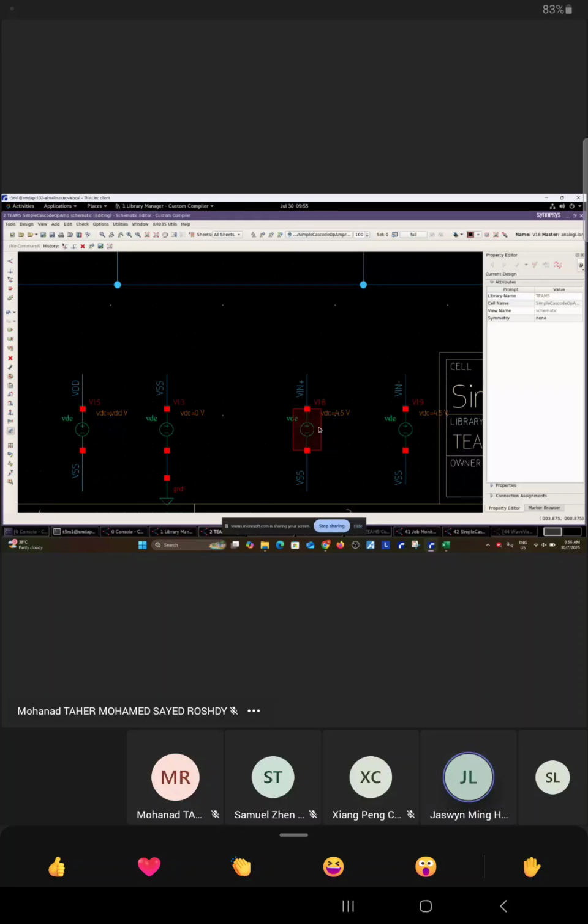You can just pick a few points like 5, 10, 15, and see whether all the operating points of your MOSFET are still in saturation or not. If the two extreme points are in saturation, I think you can more or less say the middle ones are all good already. Okay, so this one later on.